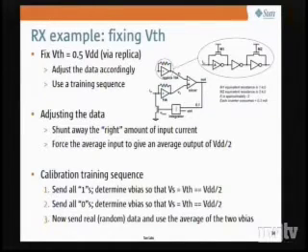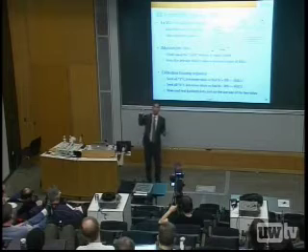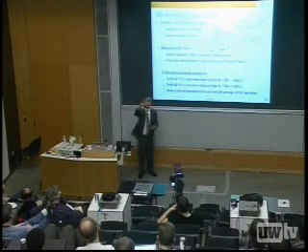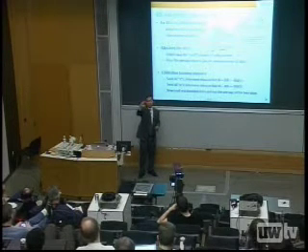Next, I'm going to send all zeros. All right, and when I send all zeros, that's a low value, and then I'll reduce this bias so that zero is artificially pumped up to half. Okay, now I've got 2 bias settings. I have 1 bias setting that forced a 1 down, and 1 bias setting that forced a 0 up. So now I'll take the average of those 2 bias settings, and that will force a 1/2 to be at 1/2. And that forces the 0 and 1 to perfectly straddle VDD over 2.